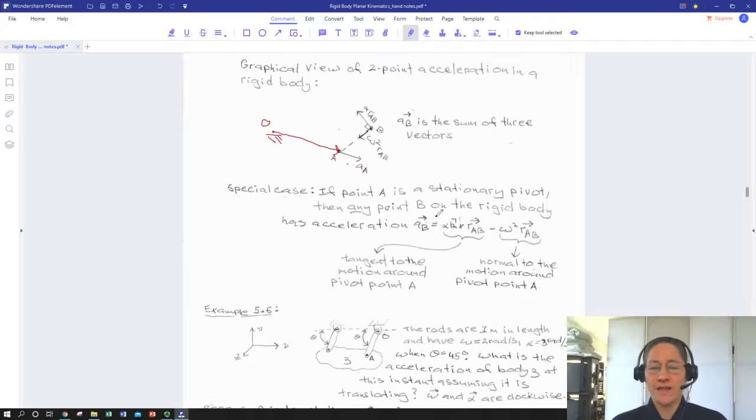And we're left with the acceleration of our other point on our rigid body B simply being a function of the rotational parts of that rigid body. So basically the body's not translating, it's just rotating. But that rotation gives any given point, other than A, some actual translational velocity components versus our fixed reference frame. So that's just a quick variation and a little thought experiment about what happens if you pin one point of a rigid body down but just let it rotate versus an external reference frame.